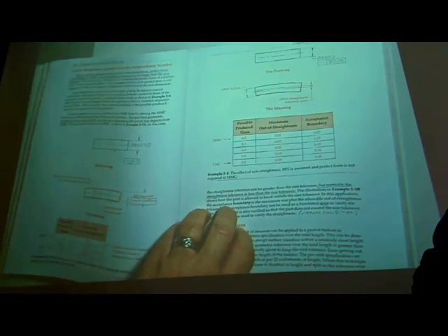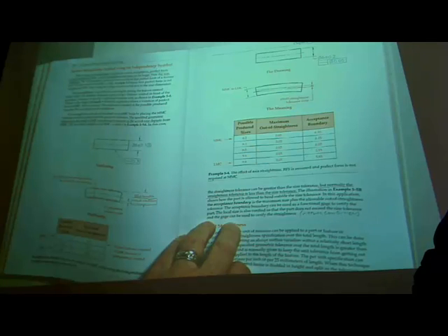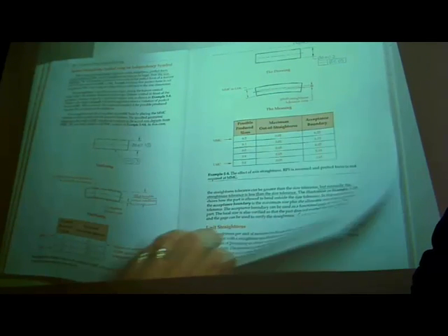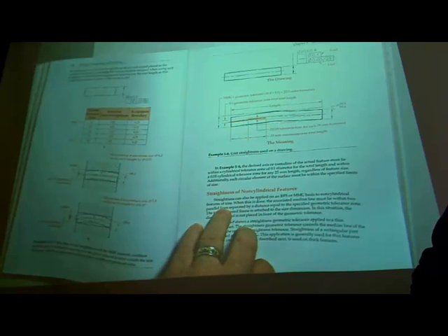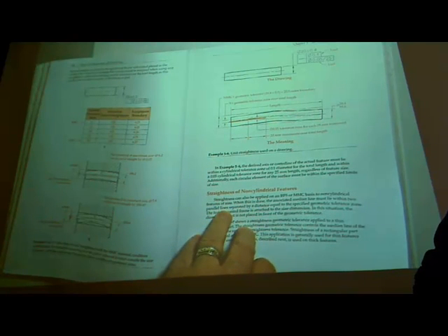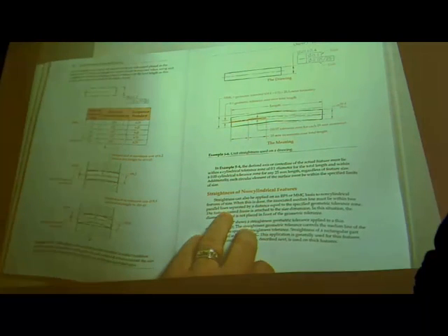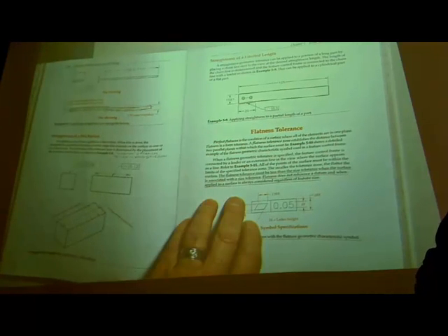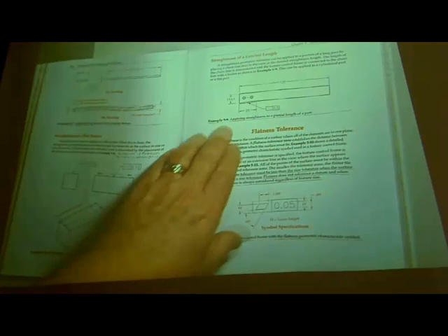We can apply it to the axis and use MMC. We can control a unit of measurement and apply straightness to it. And then over the whole length, or just a portion of a part can have straightness control.